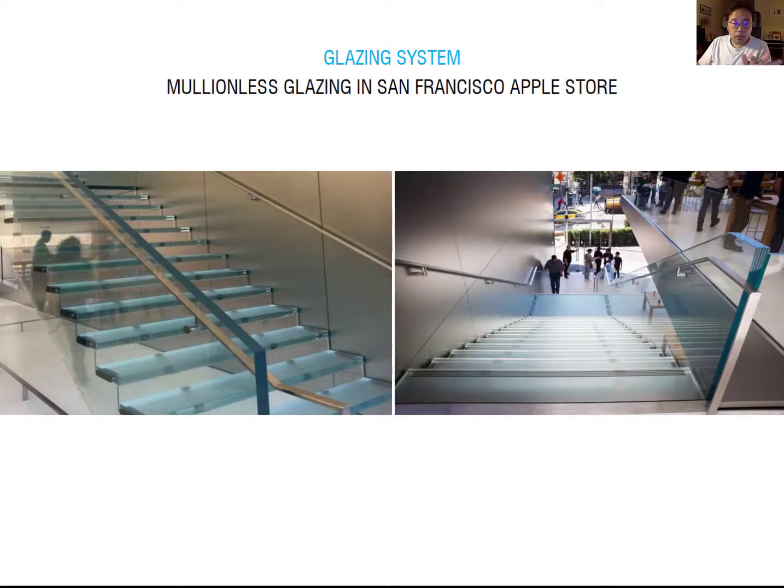Even when you see the famous Apple glass stair, you can see the glass guardrail and the glass steps. You can see they have 5 different layers together, making the stair and the guardrail. So a single layer is hard to support the weight. That's why one way to make stronger glass is using tempered glass, and it also has to be sandwiched together, which is laminate glass.